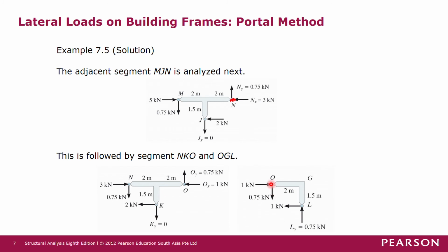Okay, so this joint O is common in these two free body diagrams. So the forces must be the same magnitude but opposite direction. So if this Oy is upward, this Oy must be downward. And then using the two equilibrium equations, we may solve for Ly.